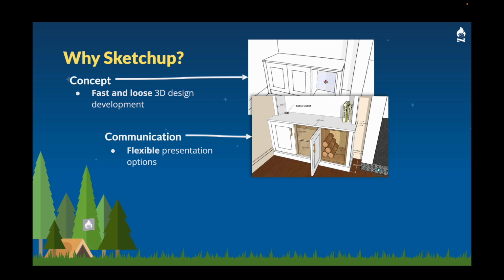It's also excellent as a communication tool. You have a lot of flexible presentation options. You can create a drawing, add as much detail to it as you want, and create different scenes, which are different viewports or camera angles, where you can make dimensions show up only in one particular scene, but you're always working off the same model. So I find it very, very quick to present to the customer and other interested parties direct from the 3D model in SketchUp. It also has powerful options to output to architect style layout drawings using a related program called Layout.